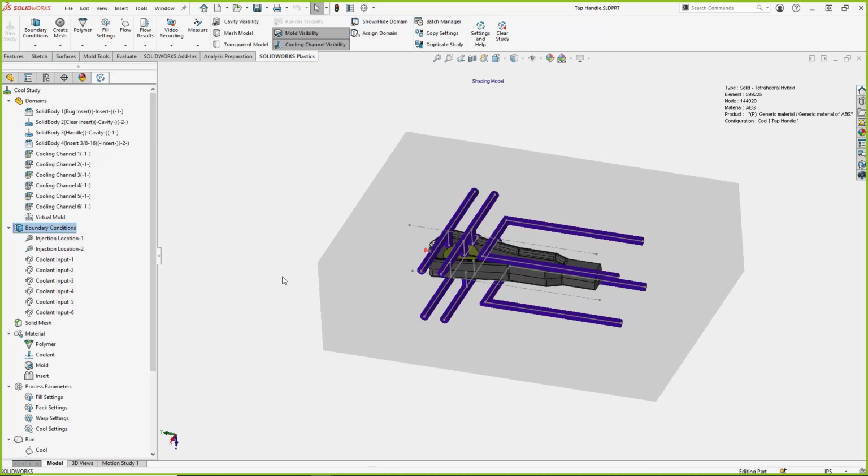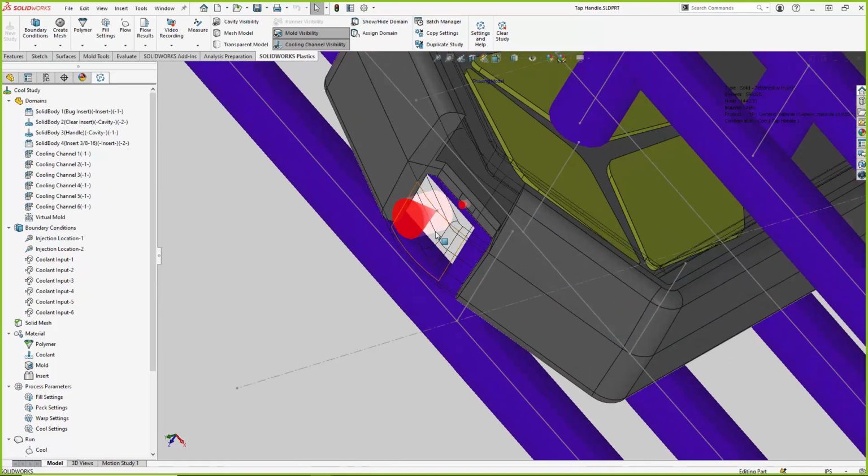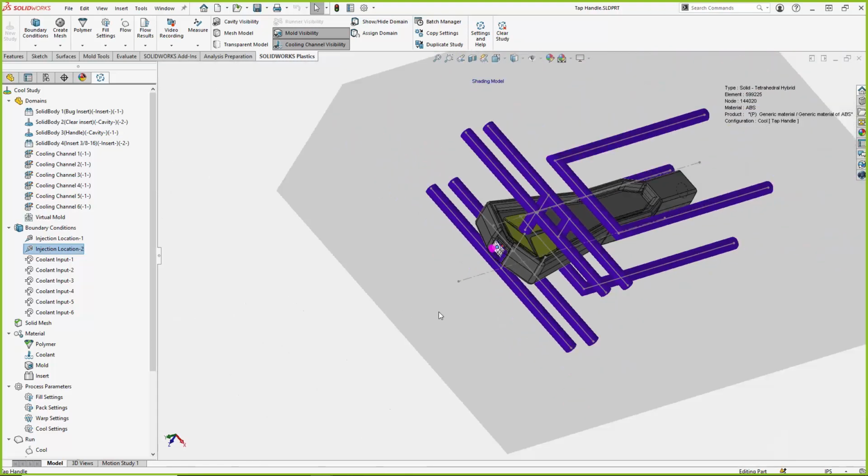So with this model for multi-injection, remember we're molding this part of it first. We're molding the solid body, the darker plastic, first. So we have to set up that injection location first on our model. And then it rotates to the other cavity and does the other injection location. So we set up 2 different injection locations.